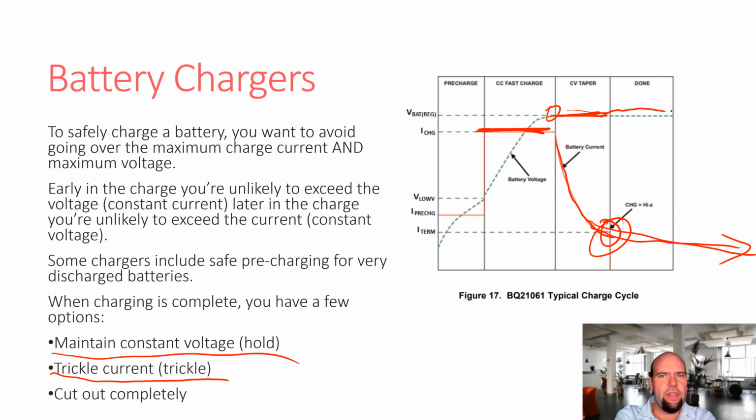That's less common with LiPo. LiPos don't really like that much. But you'll see that a lot with lead acid batteries, where they're like, "Yeah, I can handle it. As long as you only have half an amp of current, that battery can take a half an amp even when it's full all day long. It'll make a little gas or whatever, but don't do that." Different battery technologies have different levels of robustness. Lithium polymers typically don't like to be overcharged. They don't like to be undercharged either.